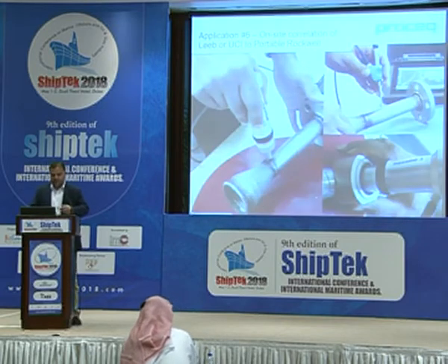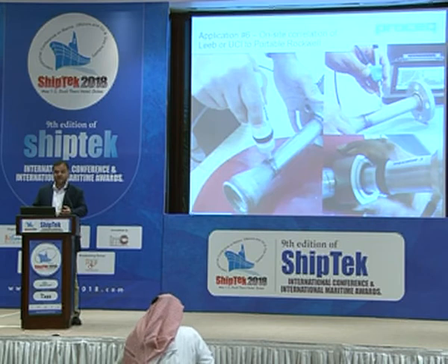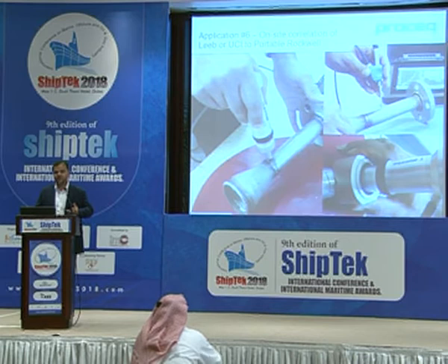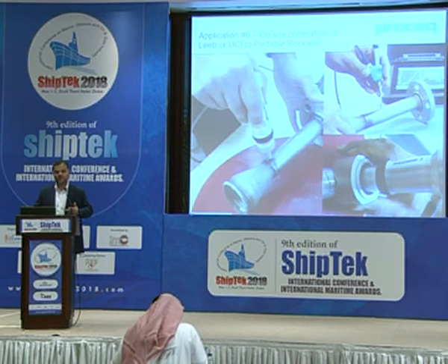Number 6, on-site correlation for LEEB and or the UCI or to the portable Rockwell. This is also one of the, as I said, the ASME and the NORSOK reports, they strongly recommend combining the different hardness techniques because there are different applications. When the samples are very thin, less than 1 millimeter, less than 2 millimeter, 3 millimeter, in that case, the portable hardness, the Rockwell type is the best suitable technique. It's static and gives more reliable data.